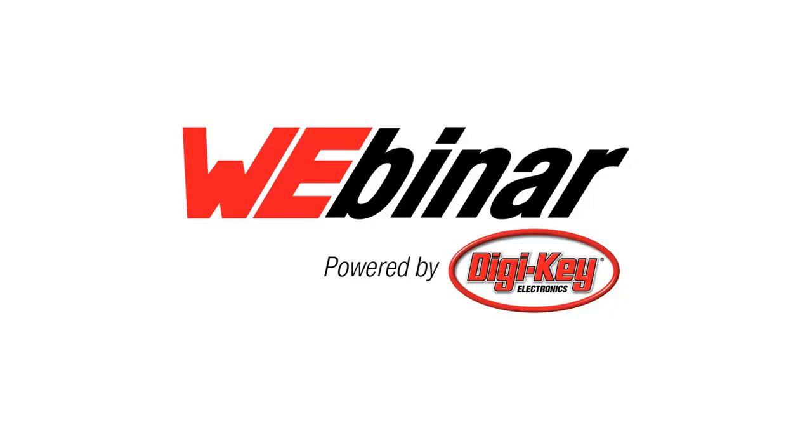I didn't get into this detail in the presentation, but based on the value of that pull-down resistor, it can also provide some information about what the sink is able to provide by default for current capabilities, giving some insight into the sink side. But based on the cable orientation, only one of those will be pulled low on the sink side and high on the source side.